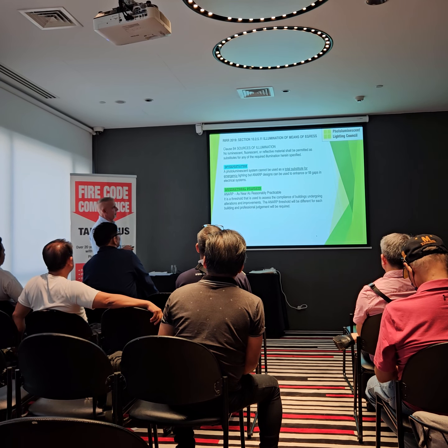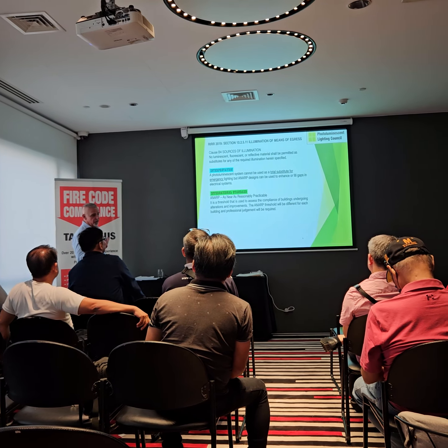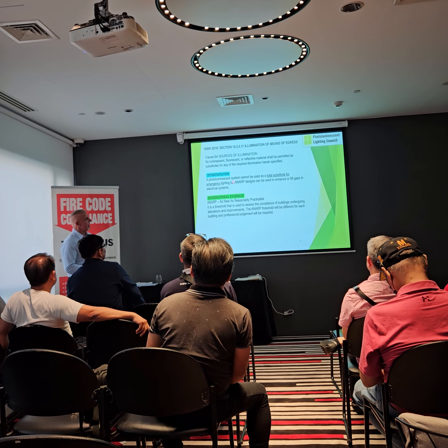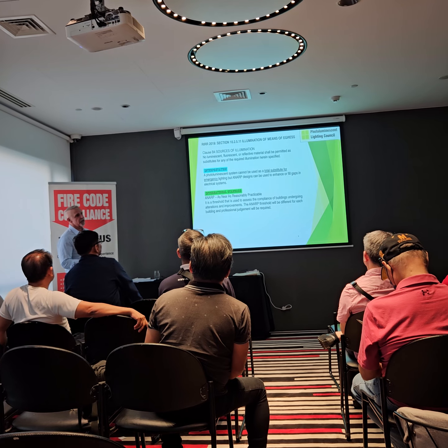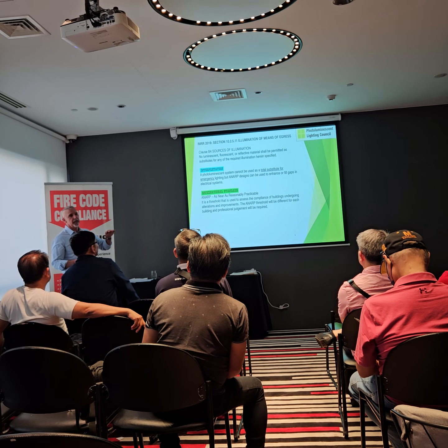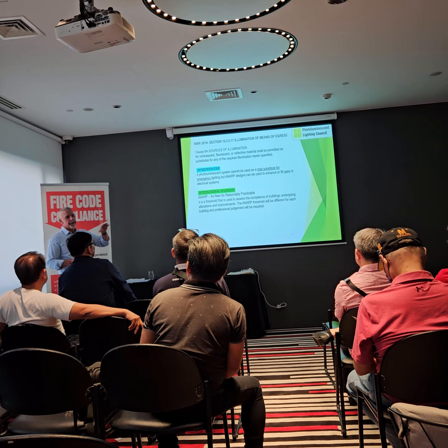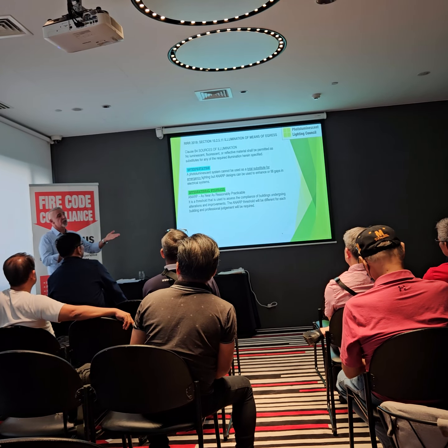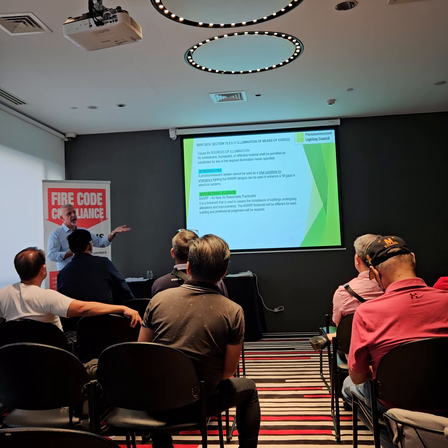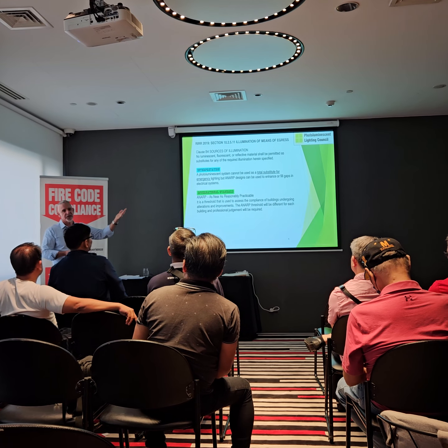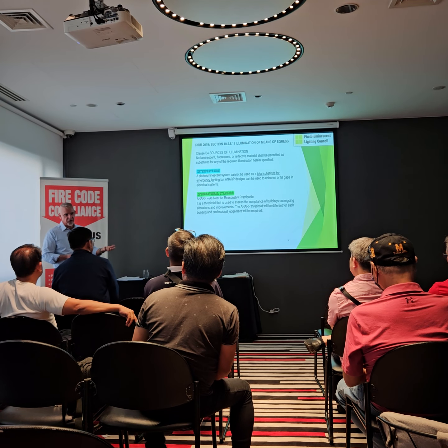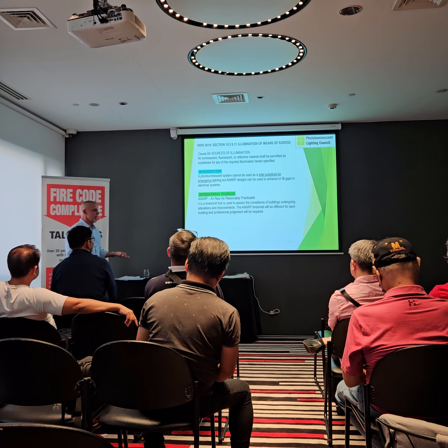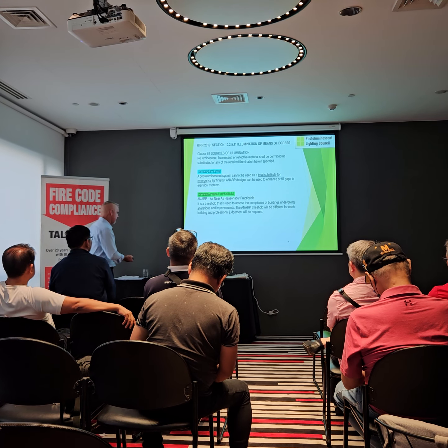But if you do have an older system or something's gone wrong, we're relying on ARC, remember, as near as reasonably practical, to say you can build photoluminescent system aspects into it to actually make it safer. If there are not enough emergency lights, you can put photoluminescent material around to actually lift it up a bit, I suppose, is what we're saying.